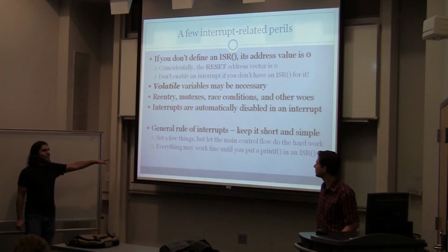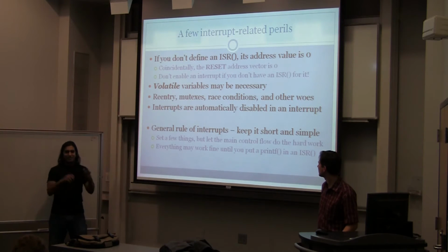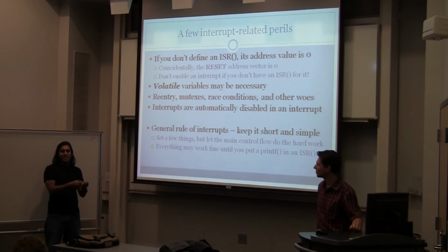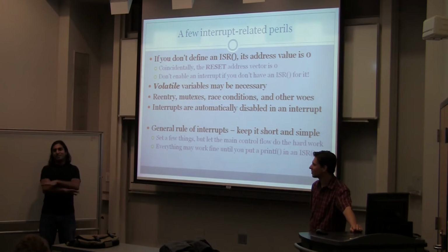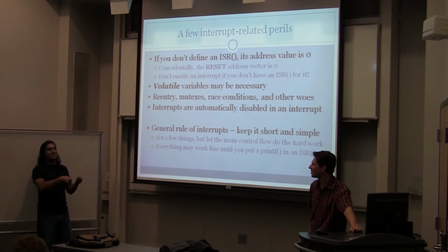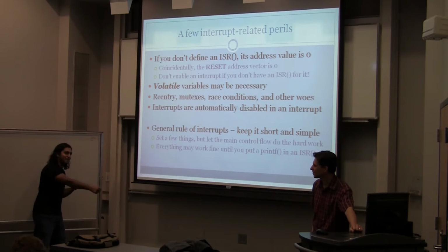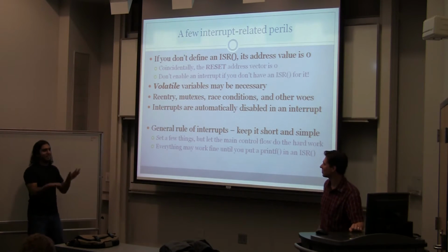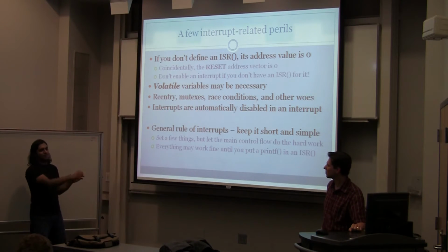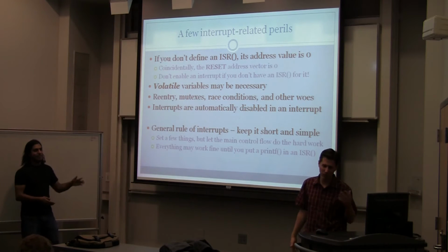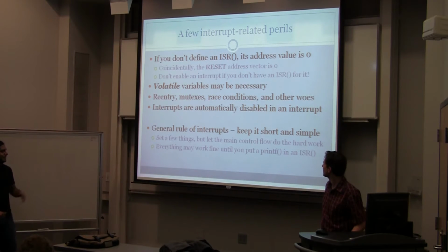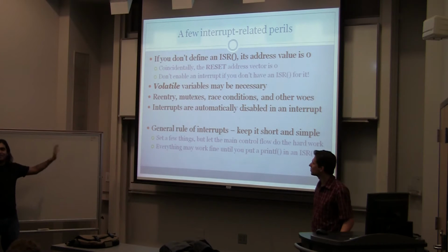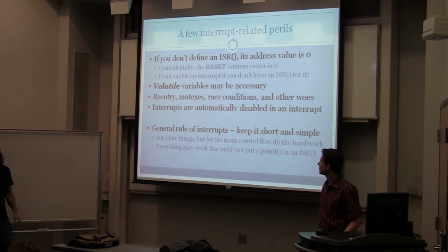To give you some idea, even something like a printf, which seems innocuous, like, oh, when the ADC triggers, let me just print out the value of the ADC, will cause major problems. Don't do this, because the printf actually has to convert a bunch of characters and then write them out to the serial stream. It doesn't terminate until every byte's been written, and that entire time, your main function is on hold, none of your other interrupts are getting called, it's just bad news. What you can do is set that value to a variable, and then in your main function, print out the value of that variable, and that'll work fine. But this is not just true for microcontrollers. This is also true in general for coding with event-based systems. If any of you go on to do that, the same caveats apply.